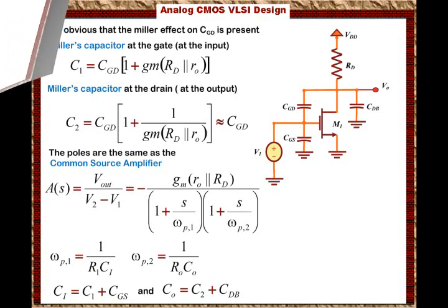Now, very interesting for us is we would like to see what happens to the common mode frequency response. Remember that the common mode says that the two inputs of the differential amplifier have the same voltage, or as the signal changes at the input, you'll experience that at the output because the circuit is not perfectly matched. So let's look at the circuit first.